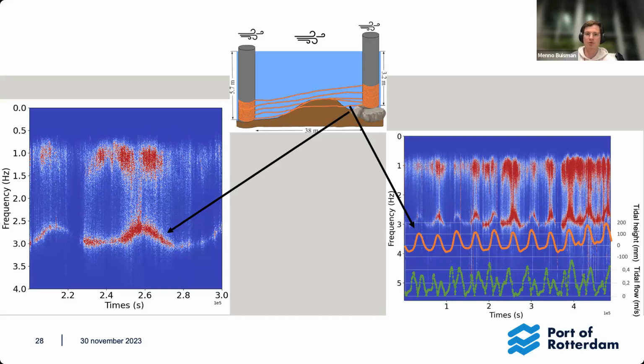But what the port authorities are most concerned about is where is water, where is mud, to say it briefly. So in my case, the muting of the signal is a very prominent feature. Whereas if we take, for instance, P wave velocity difference between water and mud, since mud is about 80–90% water, the velocities are about the same. So that's why I really go for this muting effect. This is in line with what we expected from the laboratory setup, I would say.